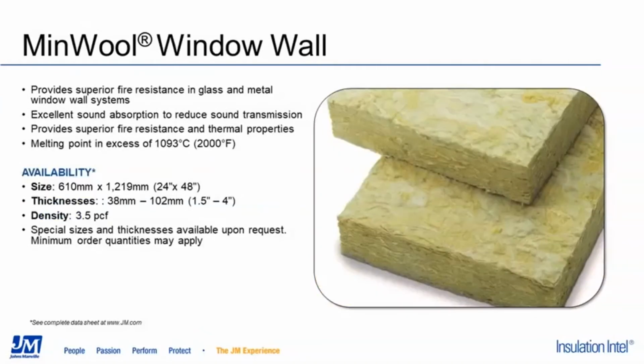Staying on the outside of the building, we have our MinWall product. This was a new product for us in 2021. This goes in certain applications, very specific applications where the cement slab of a multi-story building is going to be left exposed to the elements. That cement slab needs to be treated with a thermal insulation, and that's where MinWall finds its home.